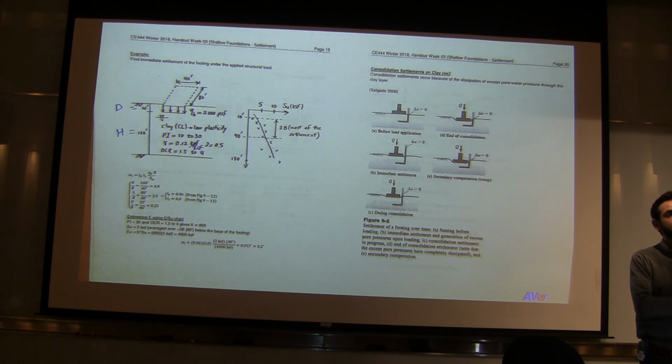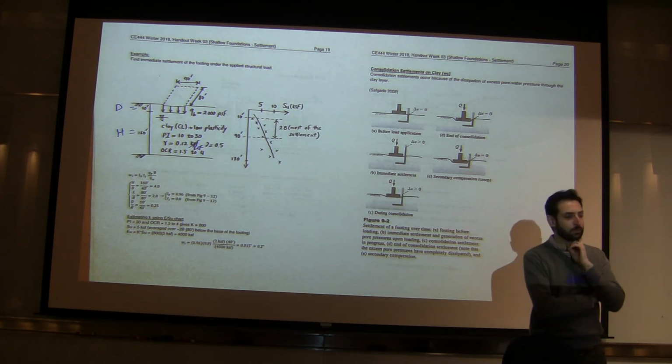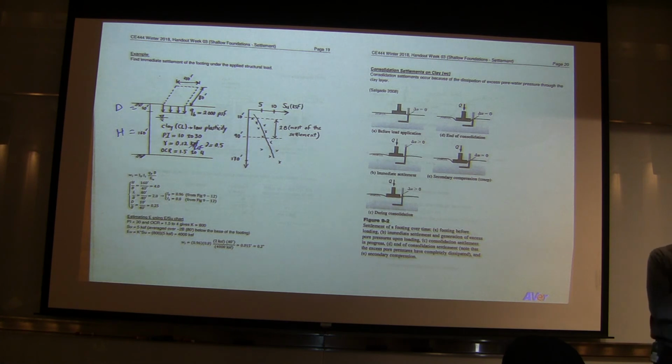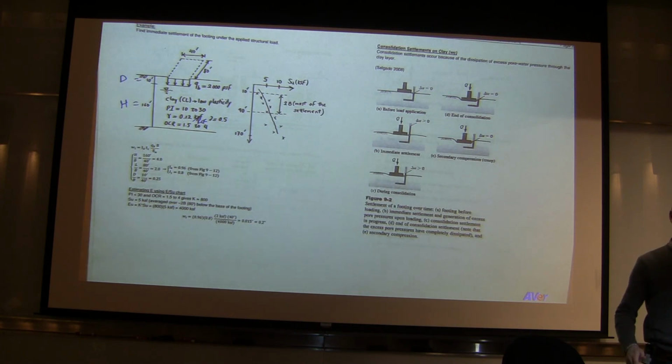Trying to remember the cases that I was involved. Yeah, we were usually asked to calculate settlements, but that's because usually the geotechs usually design for the bearing capacity. The bearing capacity is the first thing that they design for, and then we were specialized on the seismic aspect of it. So then the settlement would become more of an issue. So I don't remember too many cases where I did the bearing capacity calculation, but a lot of settlement calculation, which is heavily influenced by what's E or what's elastic modulus you.